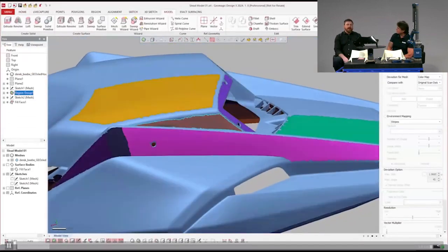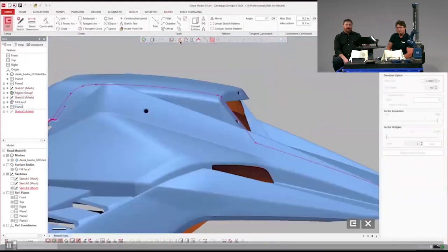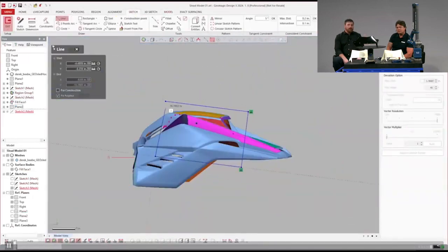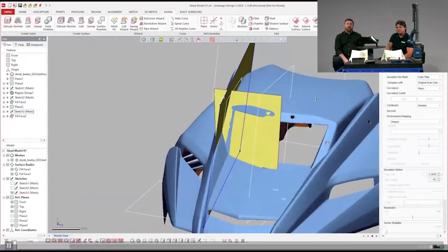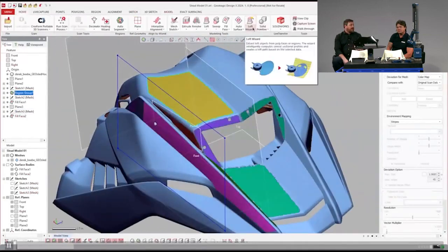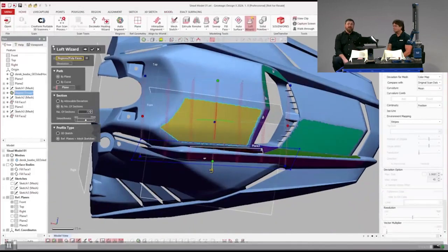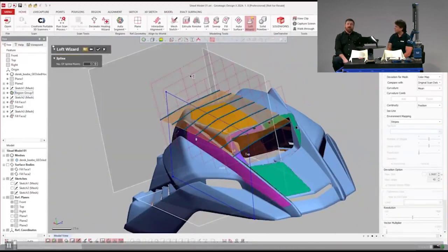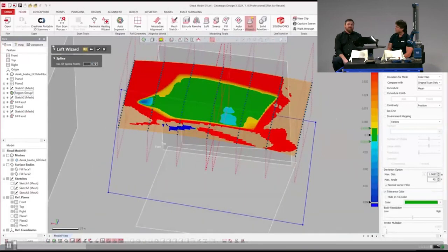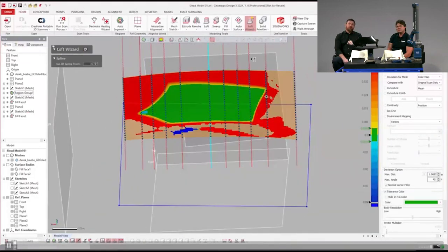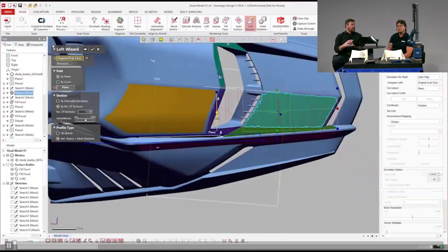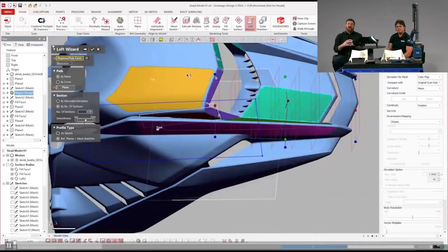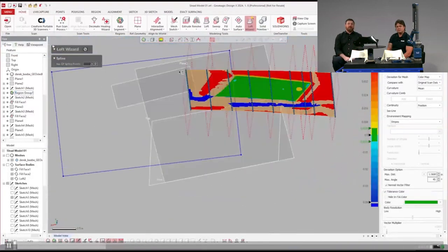So what we're highlighting now is we worked on the capture side and editing the scan data. Now we're transitioning into how I extract the geometry from the scan data. There's a lot of mystery behind this. A lot of people have questions about the modeling side, so this is usually where I get the most questions. We captured the scan data, we got great scan data. All of the tools inside of DesignX allow me to create regions, that's what those colors are. I select that region, and then we can extract CAD information from the scan data.